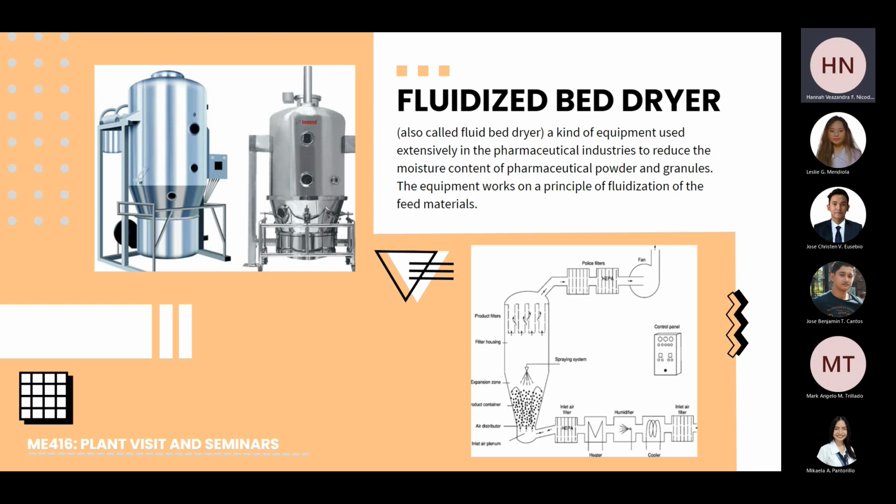In fluidization process, hot air is introduced at higher pressure through a perforated bed of moist solid particulate. The wet solids are lifted from the bottom and suspended in a stream of air. Heat transfer is accomplished by direct contact between the wet solid and hot gases. The vaporized liquid is carried away by the drying gases. Sometimes, to save energy, the exit gas is partially recycled. Next po.